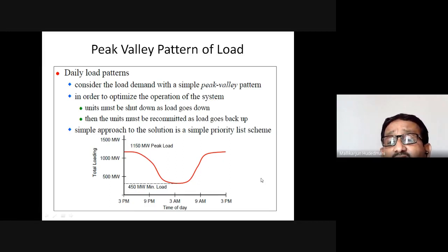And it will be rising and falling continuously because it is dynamic. It becomes very typical. Please see to it that the minimum point is the base load. This is 450 megawatt in this representation. You must run certain generators, called base load sharing generators, which will run constantly to set up a certain 450 megawatt irrespective of the changes happening here. This is called the base load generator.